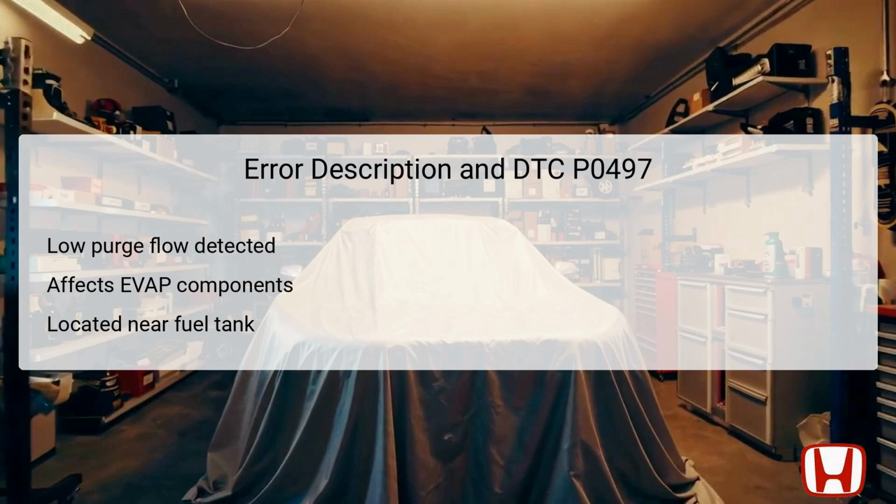The systems involved in this process include the EVAP canister, which captures and stores vapor, the purge valve that releases vapor into the engine for combustion, and the FTP sensor, which measures the fuel tank pressure. Locations of these components include the EVAP canister, typically located near the rear of the vehicle, the purge valve near the engine's intake, and the FTP sensor, usually positioned on or near the fuel tank.